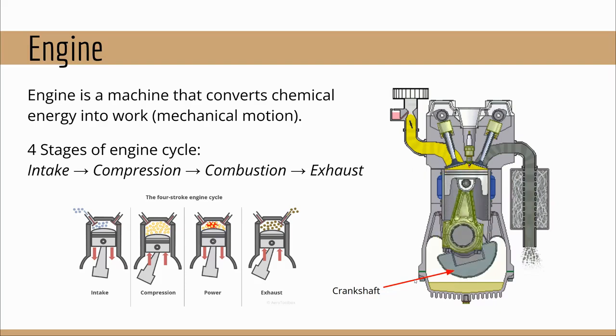At first, it goes to the stage of intake, which holds down the fuel to the chamber and then pushes up to compress the fuel, where a spark plug ignites the fuel within the chamber. It then pushes back the piston and it rotates back up to push out the gas. During this process, the pistons are doing linear motion up and down, where a crankshaft is responsible for converting linear motion of the piston into a rotating motion, which then feeds to the wheel to power the vehicle.